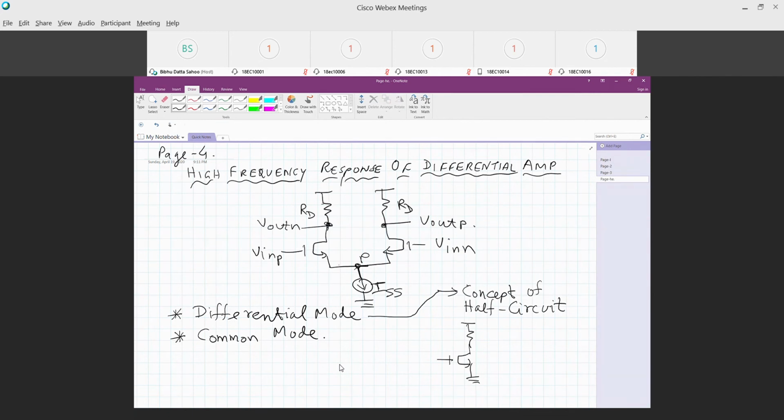Now if I have, let's say, a resistor over here, then this boils down to a common source with resistor degeneration. You apply the frequency response of the common source with emitter degeneration. Although I have not discussed the high frequency response of common source with degeneration or common emitter with emitter degeneration, because I will give that as an assignment which we will be submitting on Sunday.